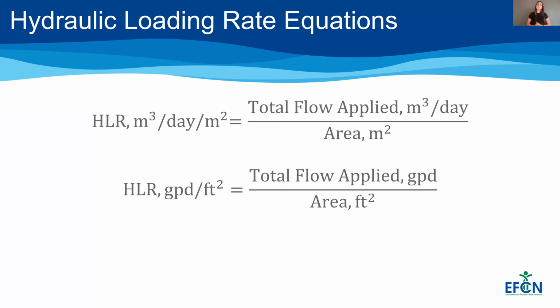So there's also hydraulic loading rate. These types of equations are used to determine if the total flow going over your fixed film media is going to be overwhelming or not.